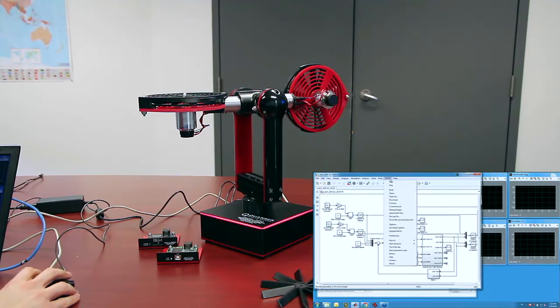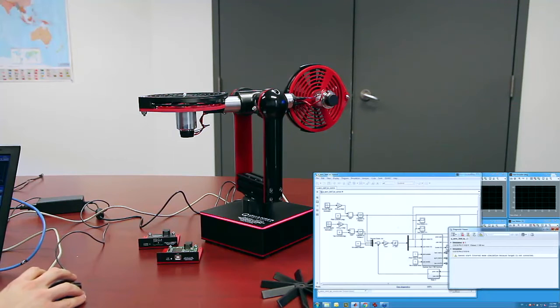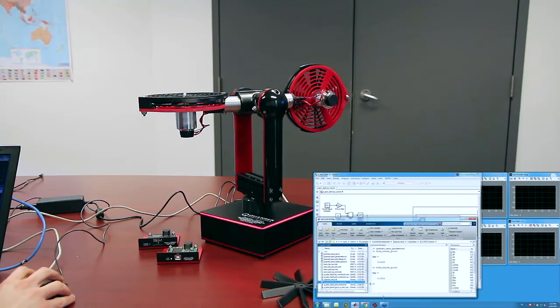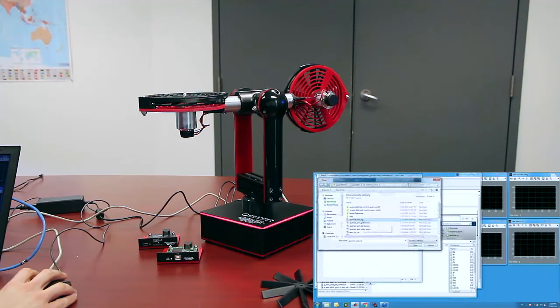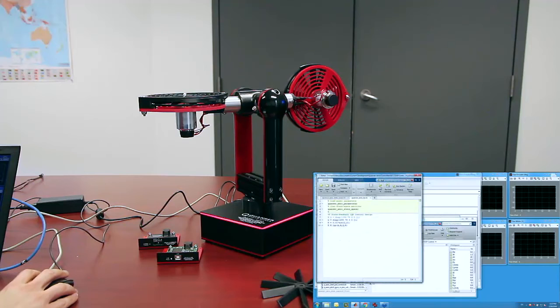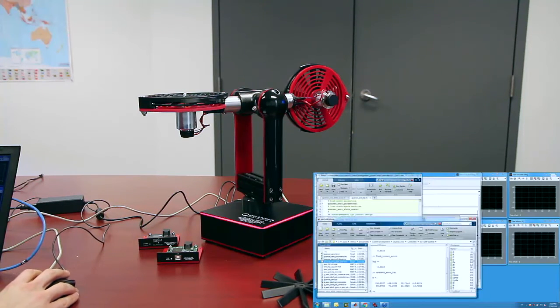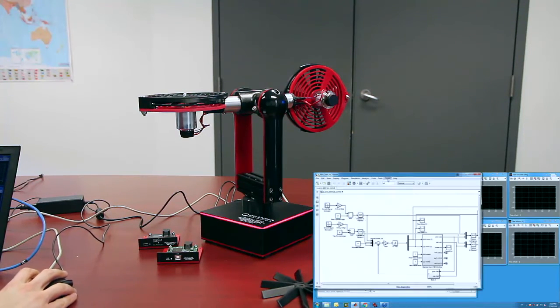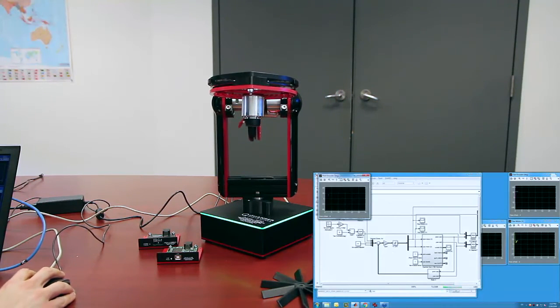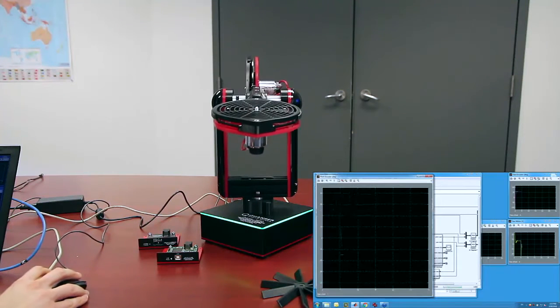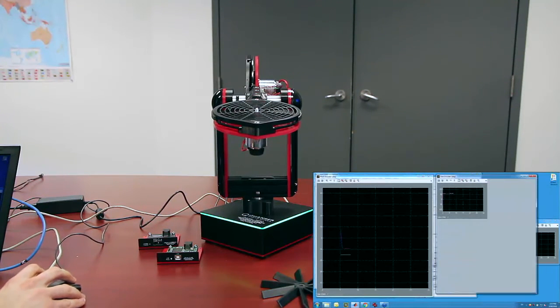So now if I run this using the same set point, so a pitch and yaw set point are the same, I'm just going to go ahead and build this. To give you an example of what we supply, some of the files, here's a state space model that we have, and then here is the LQR controller. So I'd run this and it generates my gain, and then I can go back to this and go Quarc, start to run the controller. And now let's see the difference in here. So I'm just going to expand the scopes.